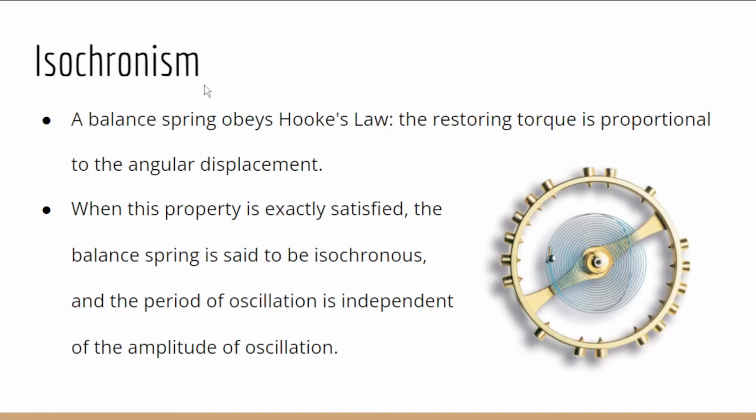Isochronism. A balance spring will obey Hooke's law. The restoring torque is proportional to the angular displacement. That is what Hooke's law tells. When this property is exactly satisfied, the balance spring is said to be isochronous, and the period of oscillation is independent of the amplitude of oscillation.